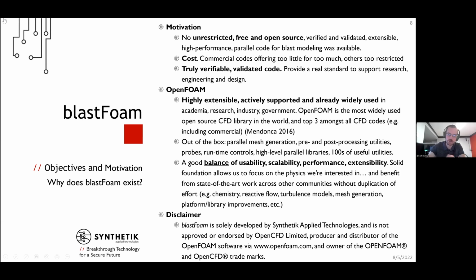So obviously we use OpenFOAM. It's exactly what we wanted. Basically, it's a great base to start everything off with. It has all of the finite volume schemes. It's easily extensible for both the finite volume schemes and the physics. It has parallel right out of the box. It has mesh generation, mesh conversion, all that good stuff.